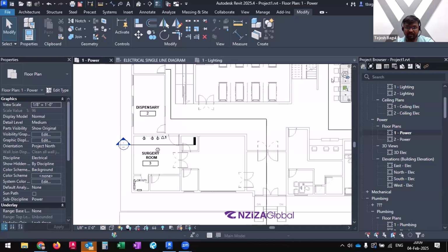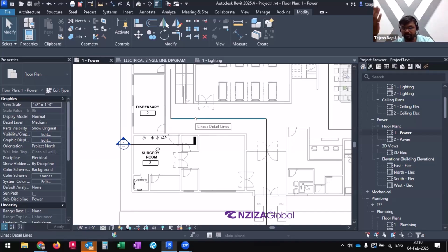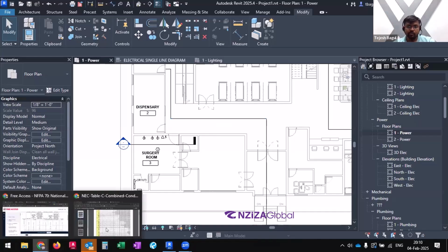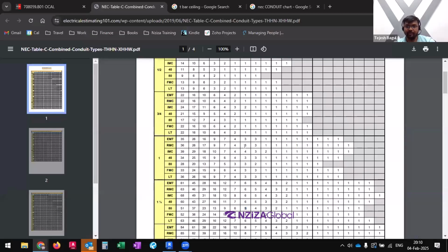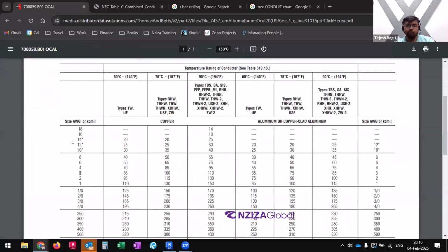Now next point regarding the conduit routing. Again, this is something that the contractor will usually do as a part of LOD 400 for fabrication. On the part of designing, when we are talking about consultancy, usually they have it as a specification, just like I told you regarding the wire sizing, right? So if the wire size is not noted on the single line diagram, then they need to use one of the wire types that you have noted somewhere in your specification, right? But just to make sure that everyone understands,